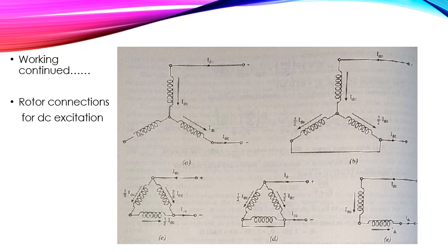As we know that in synchronous motor, damper winding is used for starting purpose to improve the starting torque. But here the exciter winding is used as a damper winding. That's why there is no need of providing separate damper winding with this synchronous induction motor.